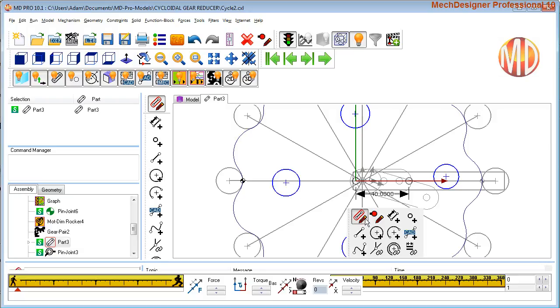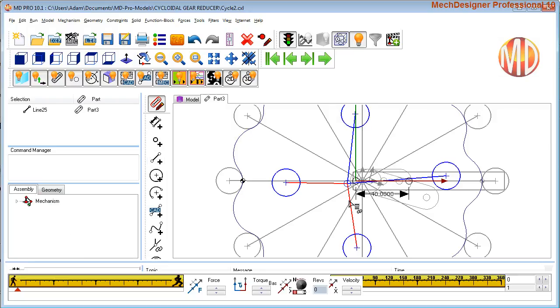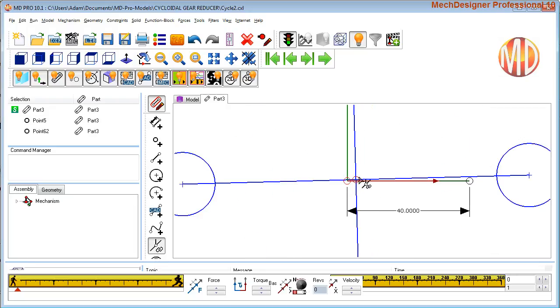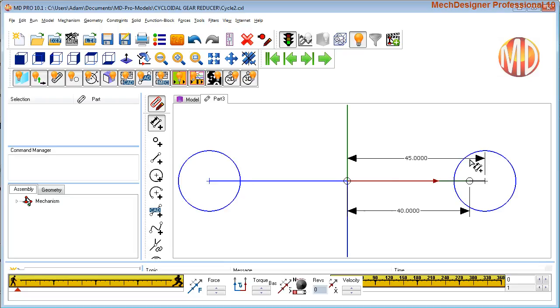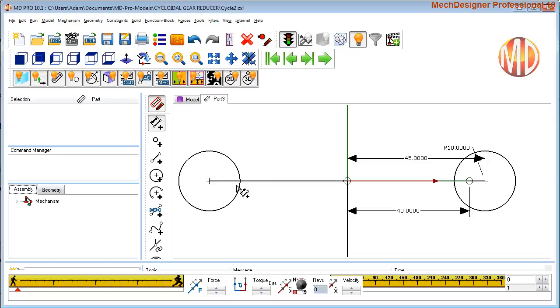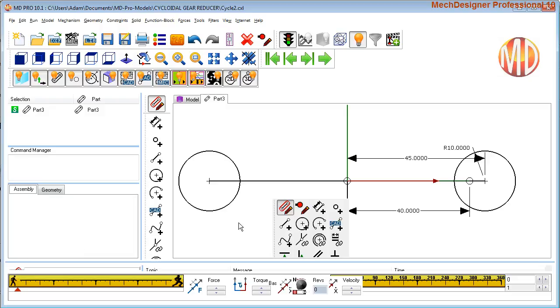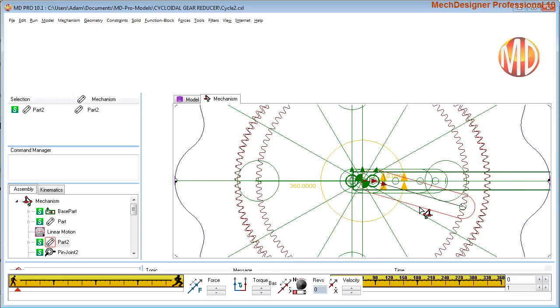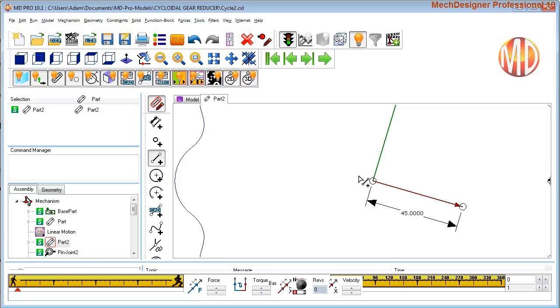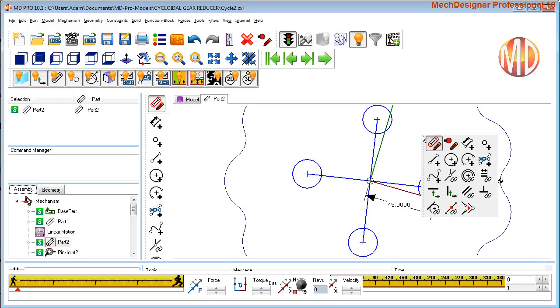So first thing we do is add 4 circles, and then I'm going to draw lines, and I want to put the circle on there, and the radius of these circles happens to need to be twice the eccentricity of the central crank, so that's 10. And we do the same on the other rotor. So let's just do this. That looks a bit more like it. Okay.